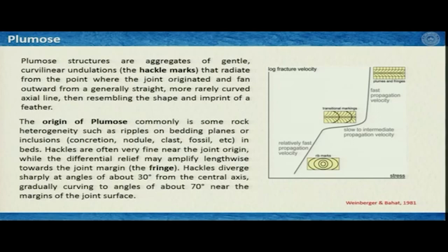Now hackles diverge sharply at angles of about 30 degrees from the central axis, and gradually this angle increases, curving to angles of about 70 degrees near the margins of the joint surface.